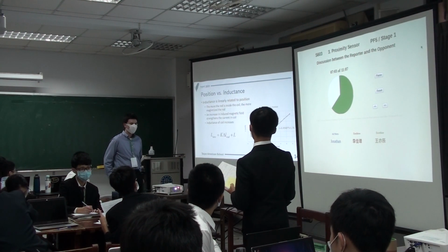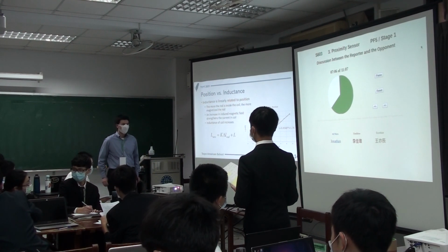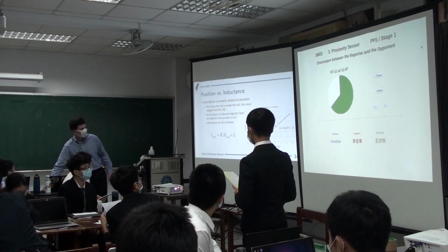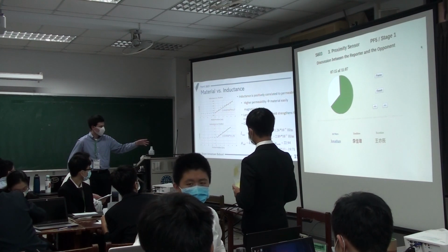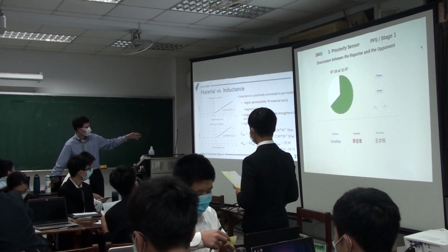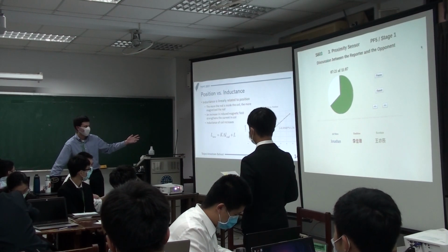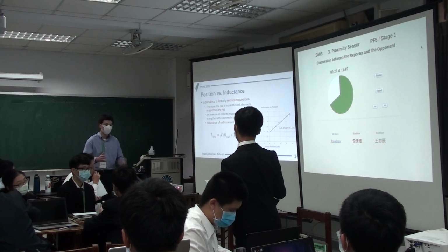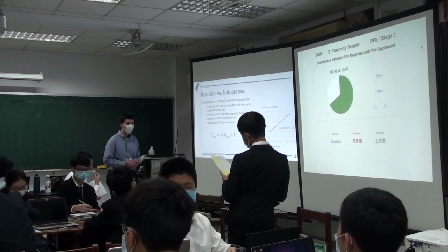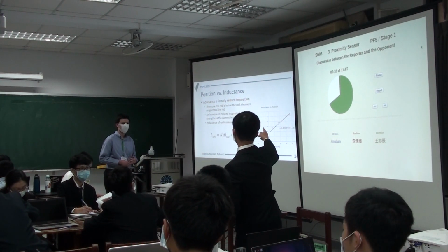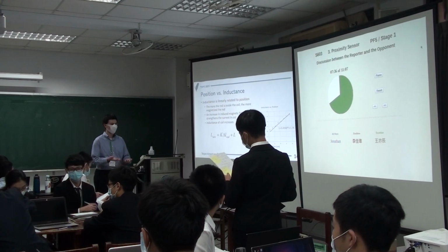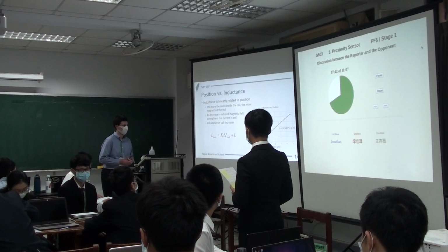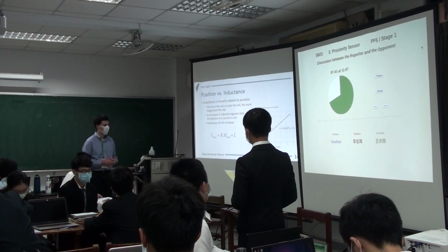But why? You can use other magnetic objects. Well, first of all, that's what we had access to, and second of all, we think that these represent two very different types of permeabilities, so we can very clearly demonstrate the effect that permeability has on the data. You can see that the permeabilities are very different by about an order of magnitude. So do you think if I use nickel alloys it will change the experiment data? Well, probably, because that would change the permeability of the material, and that would certainly change the slope of that line and how much the inductance changes.